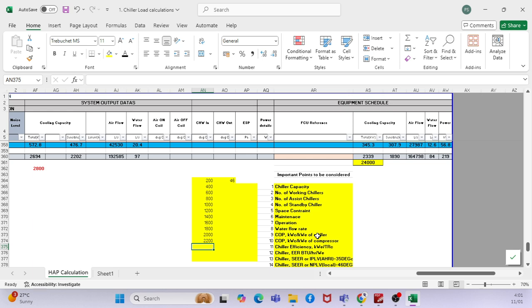When you go for different cooling, it may have a different supply temperature, inlet temperature, or outlet temperature. You have, for example, high temperature chillers, or different delta T. If you speak to the manufacturer, they have different ranges. Some chillers will operate at 7-12 degrees Celsius, some at 10-15, 10-20, or 15-25. For comfort cooling, we normally require 7 degrees as the chiller outlet and 12 as the chiller inlet. That is one of the requirements.